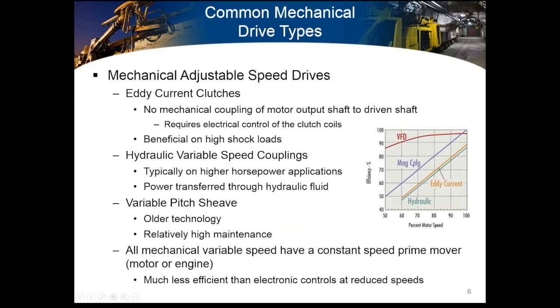It is a very good application when it comes to shock loads, oftentimes punch presses, those types of applications, or high shock type of applications. Hydraulic variable speed couplings, typically they're on higher horsepower applications as well, and the power is directly transferred through the hydraulic fluid from a constant speed prime mover to the load that you're operating.